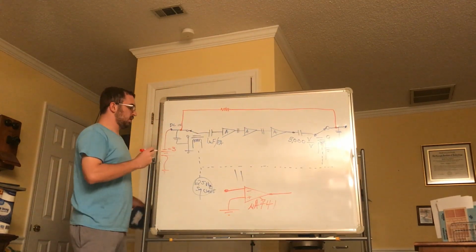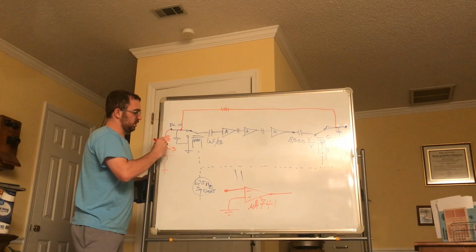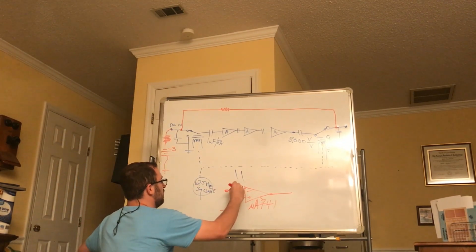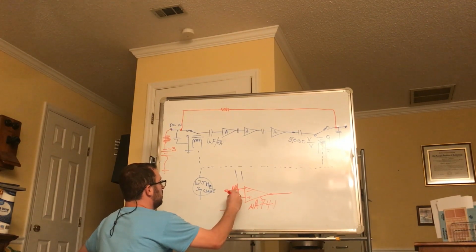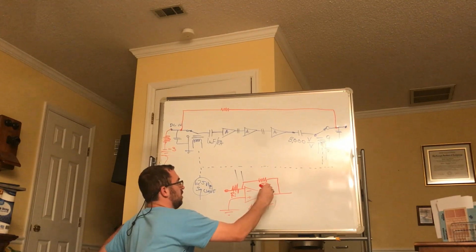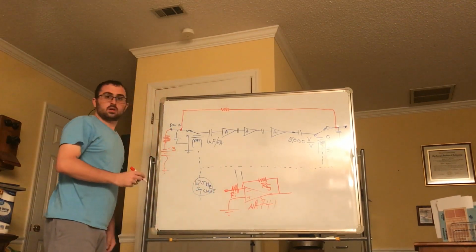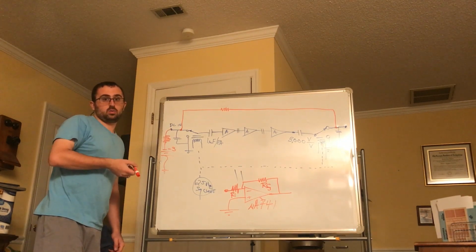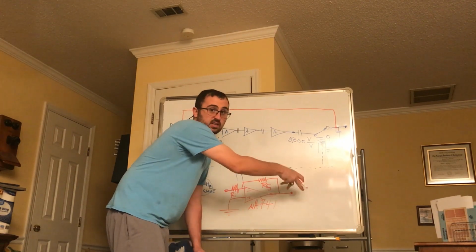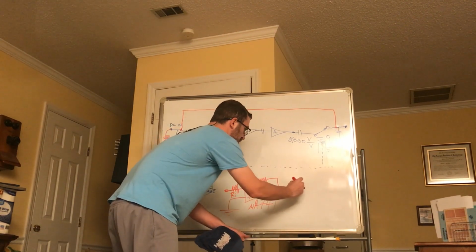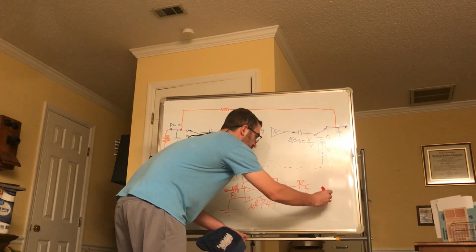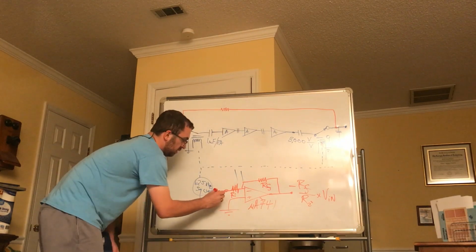There's your feedback resistor. And your traditional input resistance would go here. In that case, what we would have is an inverting amplifier, R in here, R feedback. Of course, everyone studies this circuit in Circuits 1, Circuits 2, or the like. So you know your output here. I'm sorry about the glare on this board. You can't see this when it's here. Your output here would be minus RF over RI times VN, where of course VN is between there and ground.